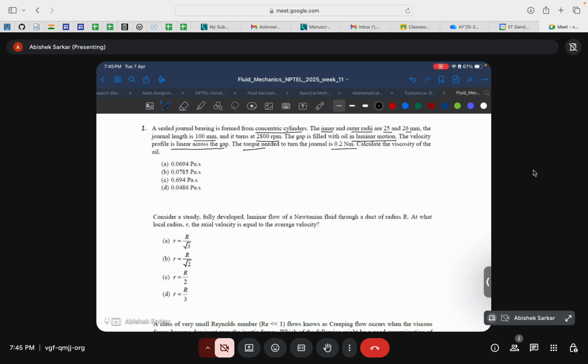Okay, it's a very standard problem in the case of flow between two concentric cylinders. But the key thing here is that in reality, if the gap is not that small and we do not impose the thin gap limit, we cannot consider the velocity profile to vary linearly between the two rotating cylinders. We are not dealing with that, and this is also not Taylor-Couette flow. I don't think we'll discuss the solution of Taylor-Couette flow in this course, though it is one of the exact solutions we can obtain. You can look into it in the textbook, or refer to other textbooks for Taylor-Couette flow discussions.